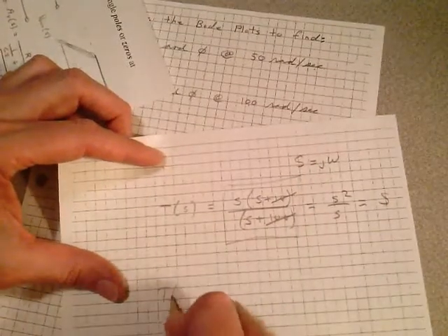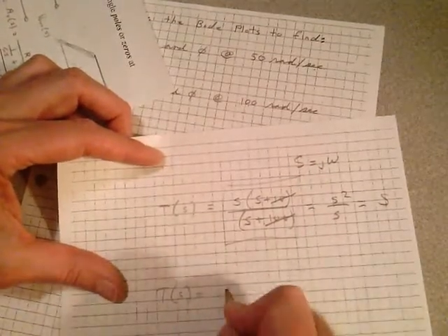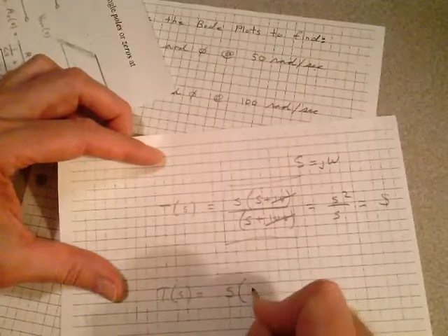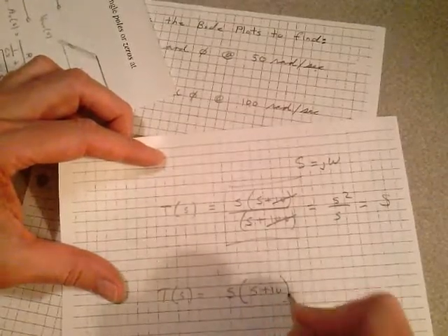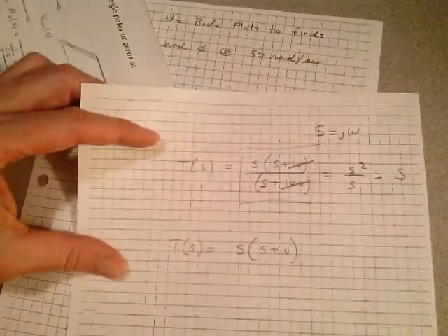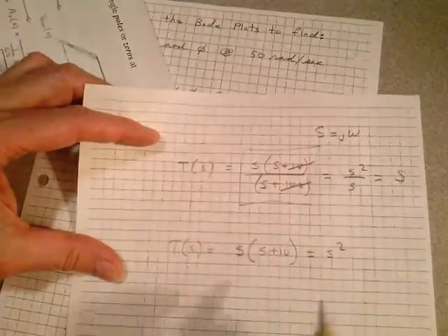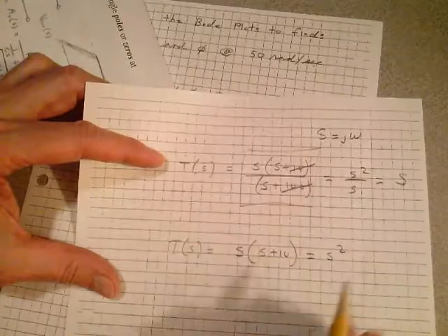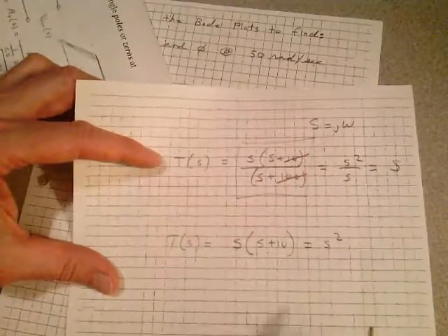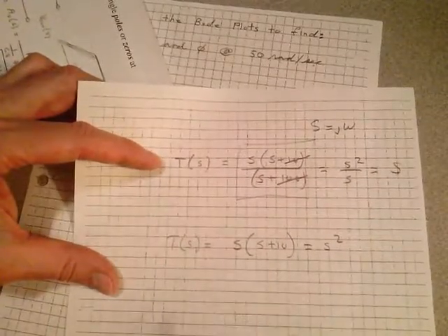Let's look at this transfer function. Well, if you let S dominate there, that's going to go to S squared. That tells me that you're going to end up at 180 degrees, and you're going to stay at 180 degrees. So that's where you should end up there.